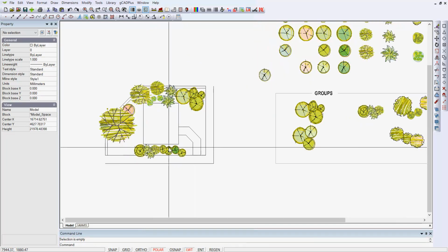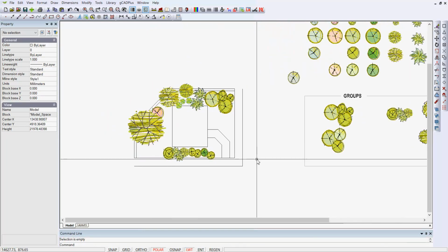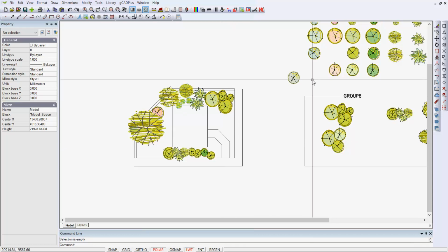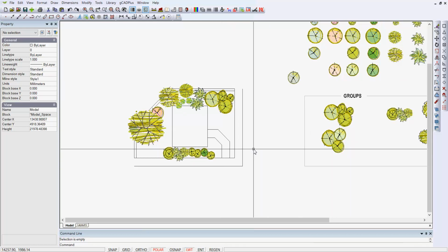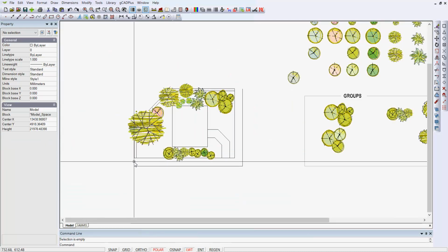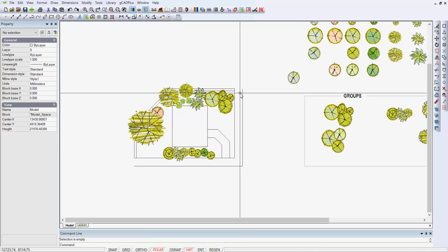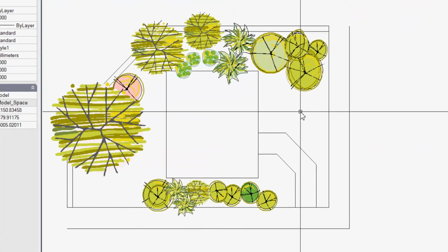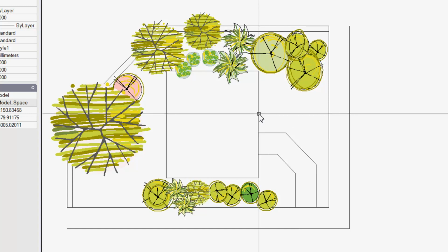So can you see we're starting to build up a concept plan, and I'll leave it to you to continue on with that. But remember that when we simply click the layout, everything that we've been doing automatically appears in that floating viewport. We'll need to deal in some way with putting a line across here, perhaps with a break in it to indicate. We might now start to dress up the paving area in here, or indicate that it's